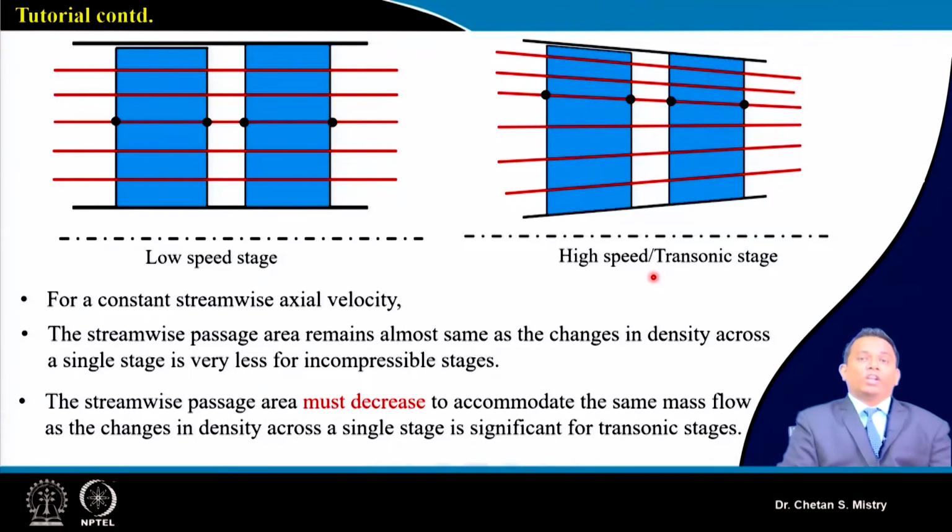Now before going into the detail, we must understand we are discussing the design of a transonic axial flow compressor. We have discussed the subsonic compressor design, in which the pressure ratio is lower. When the expected pressure ratio is lower, the inlet area and outlet area can safely be the same. That is the reason we do all our calculation at the mid station, and after that we do our calculation at different stations.